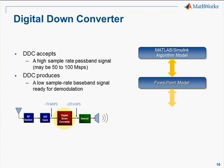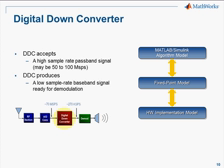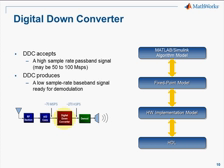From there, we'll go on to an implementation model for hardware. Using that model, we can verify whether the architectural and implementation trade-offs we're making are helping us to meet the system requirements and specifications. And we can look at tuning the design further using optimizations in HDL Coder, such as getting more serial implementations of filters, introducing pipelining, and so forth. From that implementation model, we can generate the HDL code, and we can verify it against these higher level representations. As we go through this, we certainly won't have enough time to do every single step, but we'll highlight some of the things you can encounter in each one of these levels. So let's proceed into the demo.